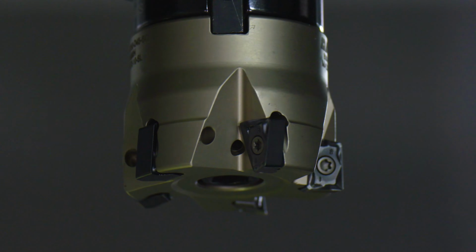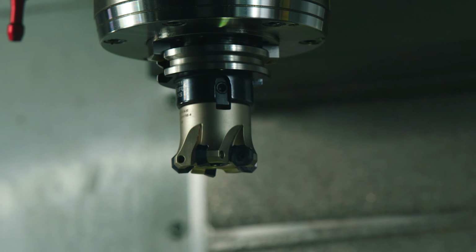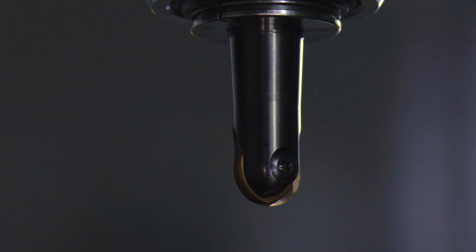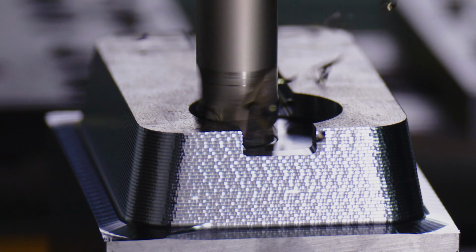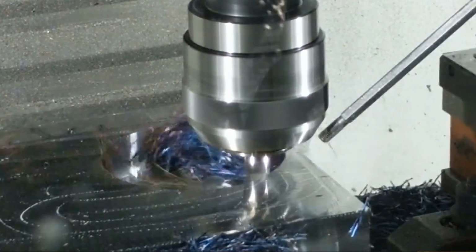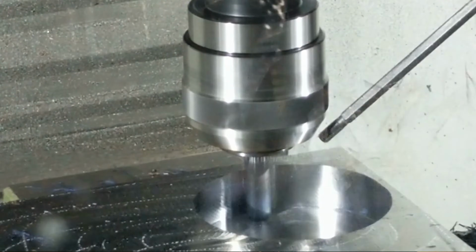As we've said before, one of the really good things about indexable tooling is the vast array of various cutting geometries available for use, from shoulder milling to high feed to button tools, octagonal face mills, ball nose and back draft finishing tools, and many more. Indexable cutting tools create opportunities to achieve high-performance material removal at low pricing, especially in comparison to solid carbide tools. With all this variety in cutting geometry, having to choose the correct cutting edge can be a confusing decision. Let's take a look at the most common options available and their characteristics.